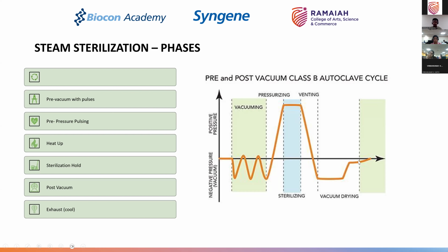So you start applying vacuum to the chamber through a filter, and with a combination of air coming in and a vacuum, what are you doing? You're removing all the moisture from the load and achieving drying. This is a methodology where you are doing vacuum drying at a condition where the temperature is falling from 121 degrees centigrade to a reasonable 40 or 35 degrees centigrade, at which you are now able to remove the load.